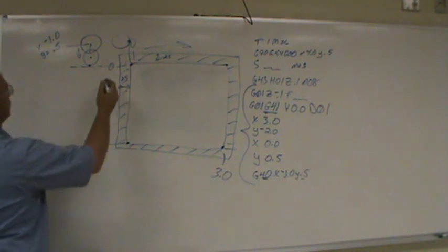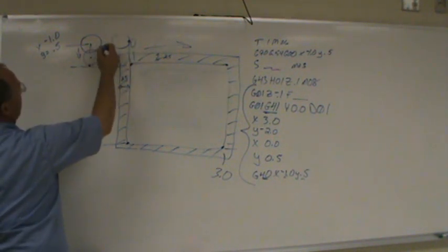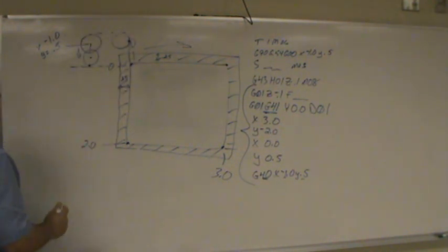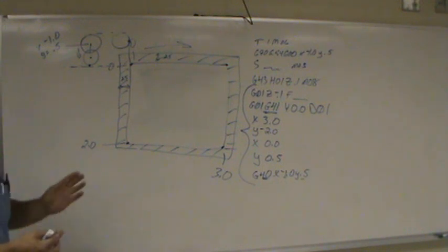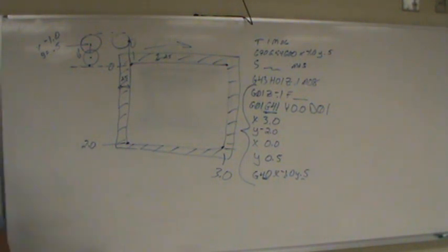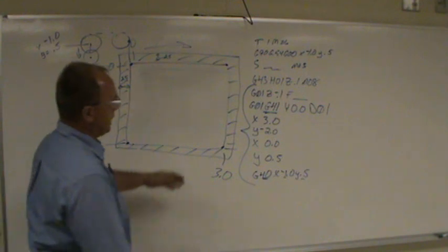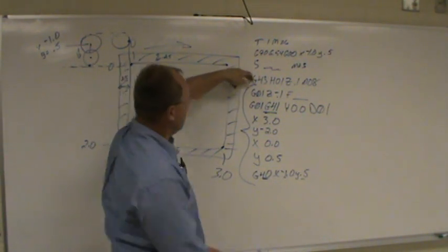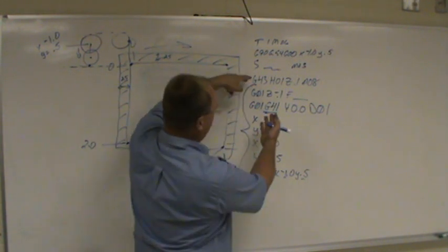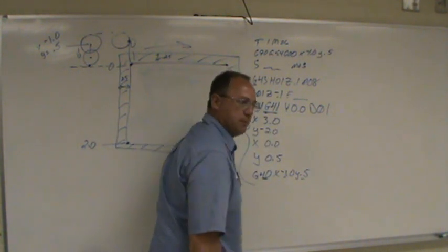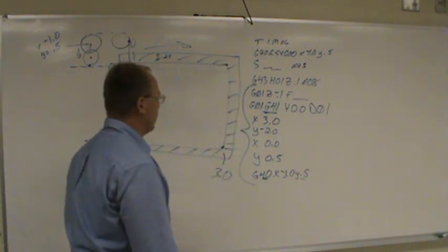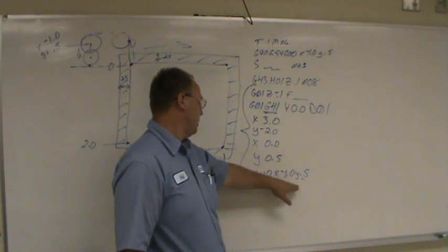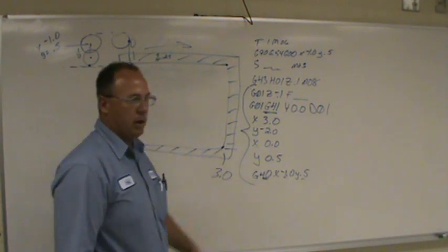Because if you don't turn your cutter comp off and you tell it to come back here, you remember that machine's always trying to keep that cutter on the left side of that edge. So it's going to start doing some funky things if you don't turn the cutter comp off. And as long as you're doing the copy and paste, it's not really any more typing. You copy this, you paste it. If I have to do 4 passes, I'm going to copy that 4 times. So like I said, the important thing every time you change your Z depth is get back to your start point and turn your cutter comp off.